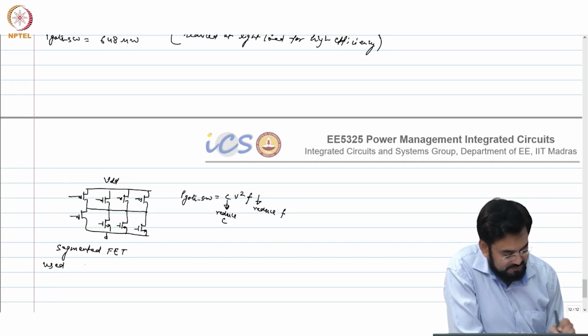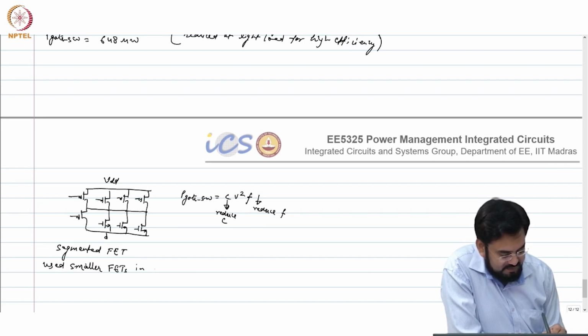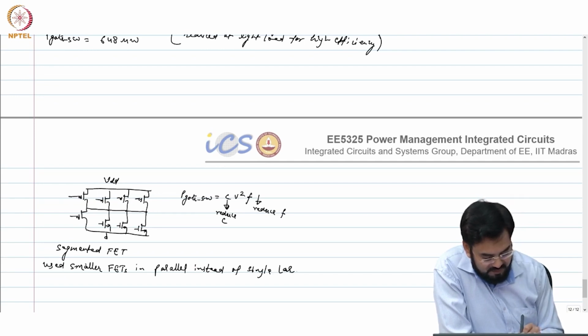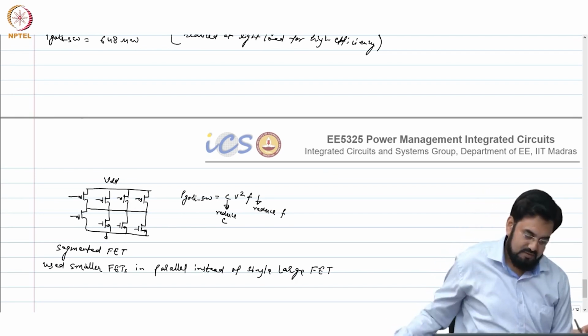Use smaller FETs in parallel instead of a single large one. Okay.